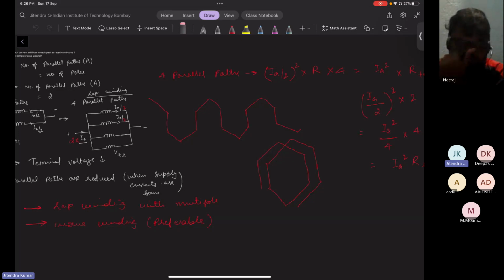So what they did was connect all the windings to the equalizer, such that any circulating current will flow through the equalizer and get out of the windings in the overhang section, right? So let me draw it for you. How does the equalizer get connected?